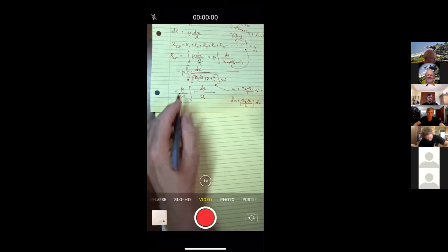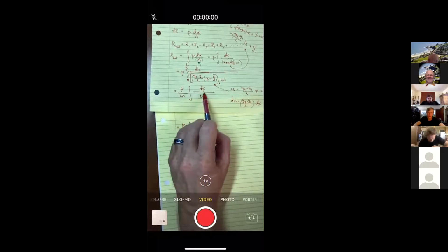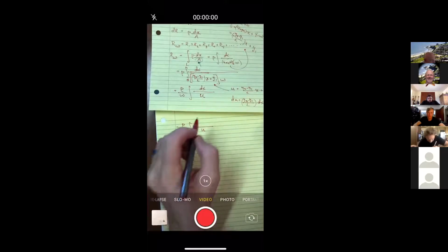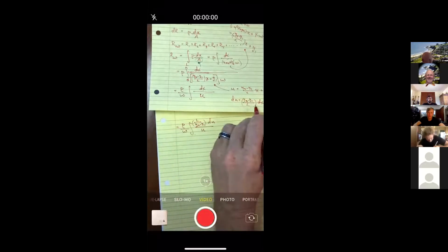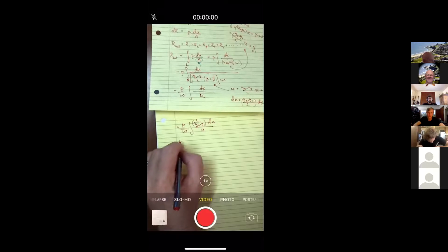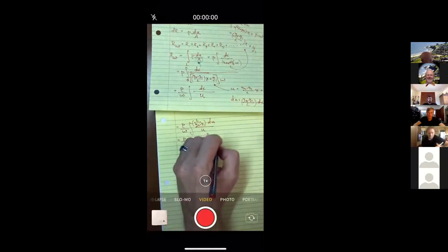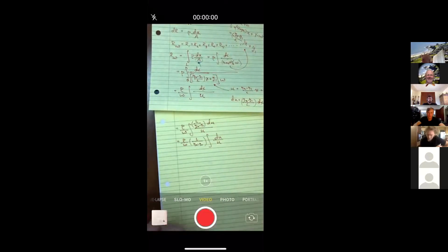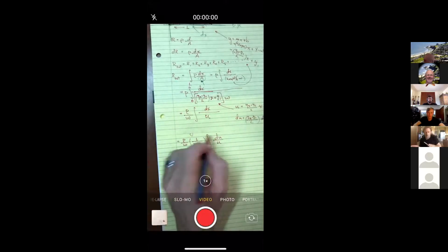So I've got the resistivity over the width, and I've got a U downstairs, but now I can do this dx substitution. Moving this to the other side, dx would be L over y2 minus y1 du. And then pulling out the constant L over y2 minus y1 leaves me with just an integral of U du. So that may not have been that noticeable for you at first, but that's what this was screaming at me. Do a U sub, and you got an easy integration.